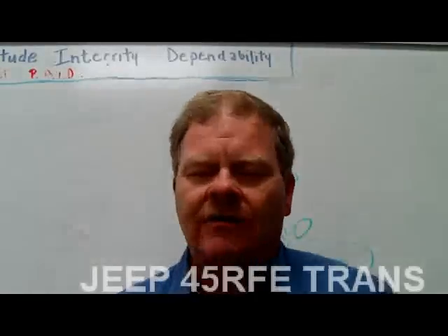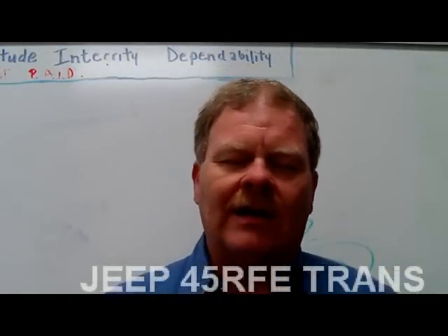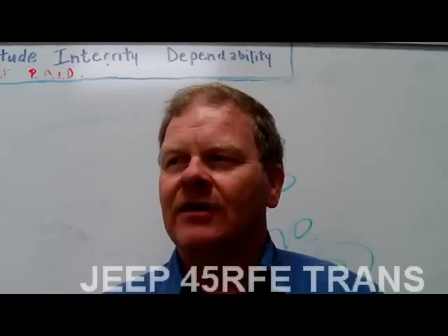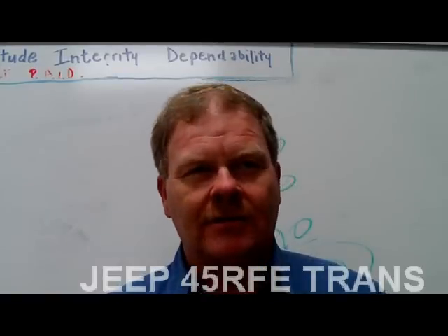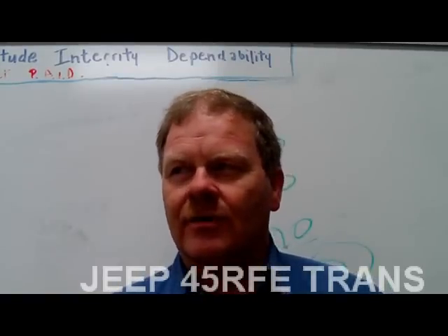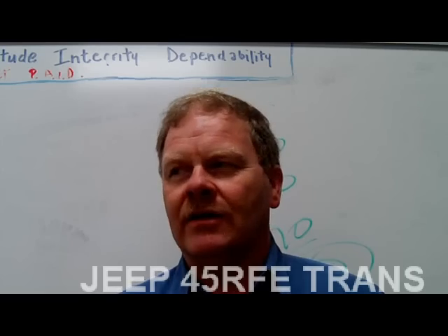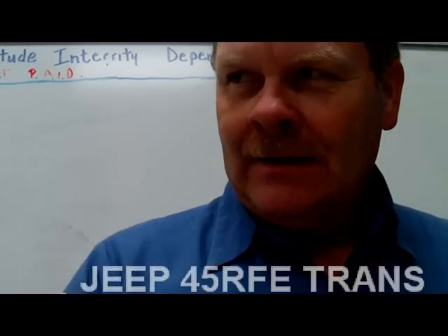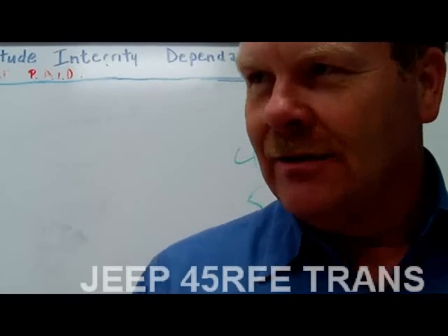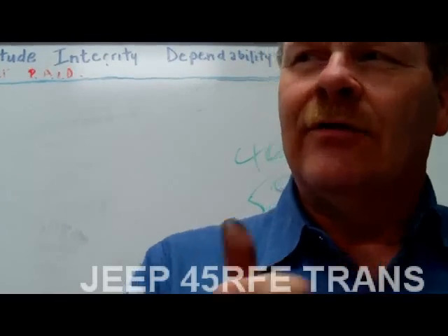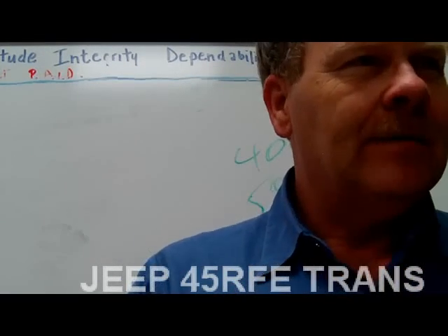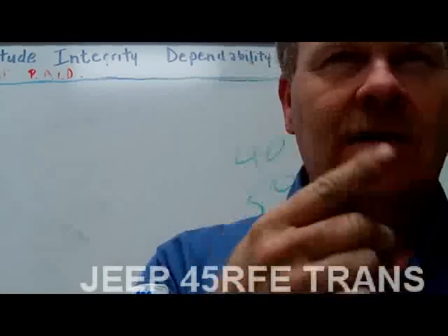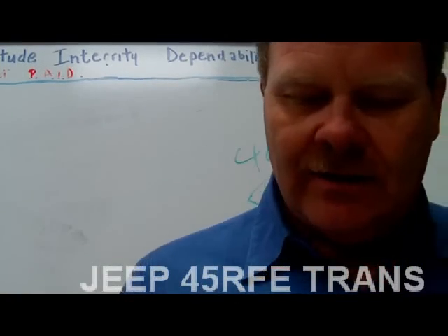It wouldn't downshift, even though the throttle angle and the engine load dictated a downshift. If the cruise control was engaged, the transmission computer would not downshift because it knows that customers are trying to save gas and they don't want to downshift. If there's any way you can make this happen without a downshift, we don't want it. And so they called that fuzzy logic, and it was programmed into the computer. If the cruise control's engaged, huh? We went over that one time. Yeah, exactly. We talked about it, but I burn it in, and not everybody's here every day. But so that's what you're talking about there.